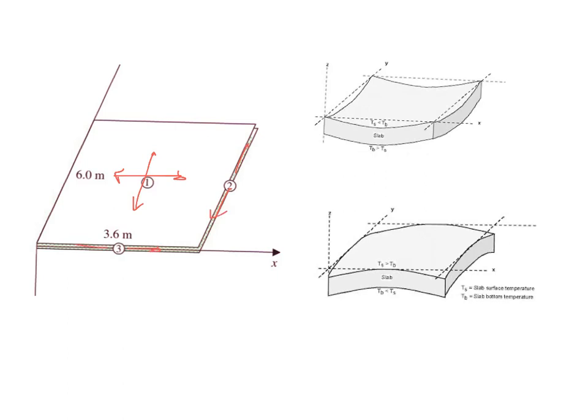These stresses may be tension or compression depending upon whether you are measuring the stresses at the top or bottom of the pavement. Because of these stresses, your pavement is going to warp in either of these types. So this warping is happening due to the stresses you are calculating because of the differences in temperature.